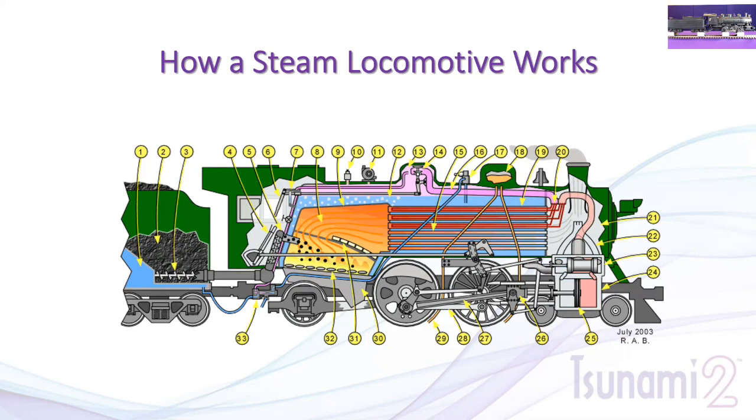And then also you notice the water line in the tender is below the coal, and basically water draws down by gravity. So you see the pipe that carries the water from the tender below the water line over to the locomotive. And then we have the injectors, which will pressurize that water and force it in through the check valves. And we'll talk about all of this here. And then of course you have your steam dome, and then you have what's called the turret.